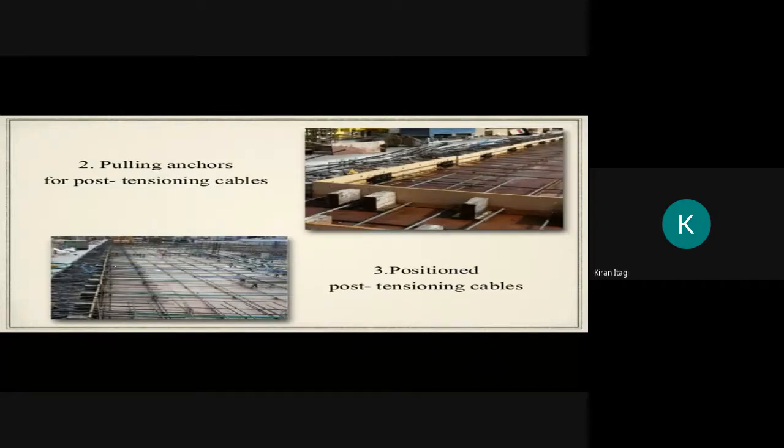Initially, this is the framework. Okay, centering work is there. They provide all the cables, and while laying the cables we have certain heights. Okay, at what height or eccentricity we have to keep, for that we call it the cable profile. Okay, this is your beam. Sometimes we provide the cable straight, sometimes like this, sometimes in a triangular shape. Okay, we have different cable profiles.